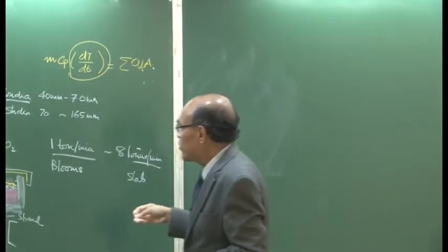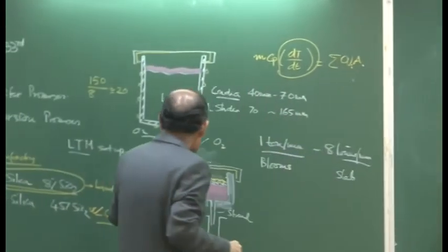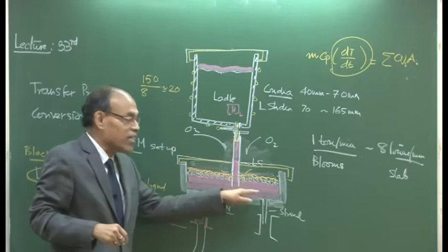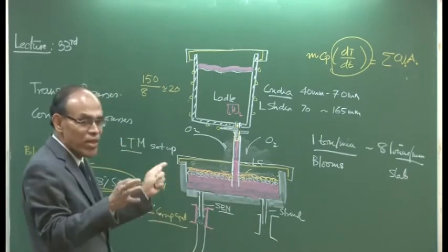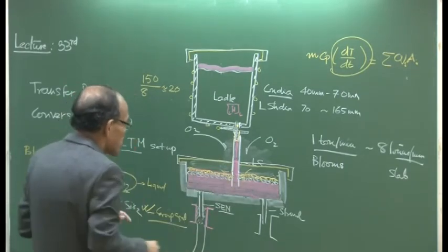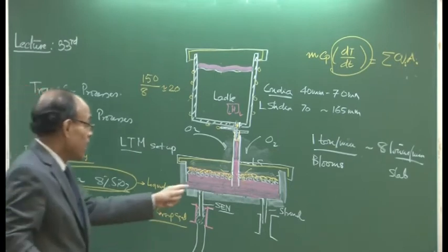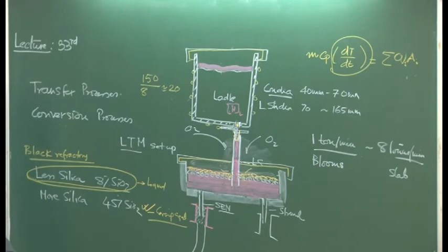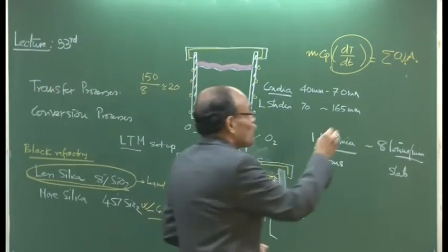The tundish, molten metal enters into the tundish, and as you can see, as I have drawn here, as if the tundish does not contain anything, it appears to be a simple kind of box type reactor, but it is not like that. The tundishes have many internal furnitures which we call flow control devices.